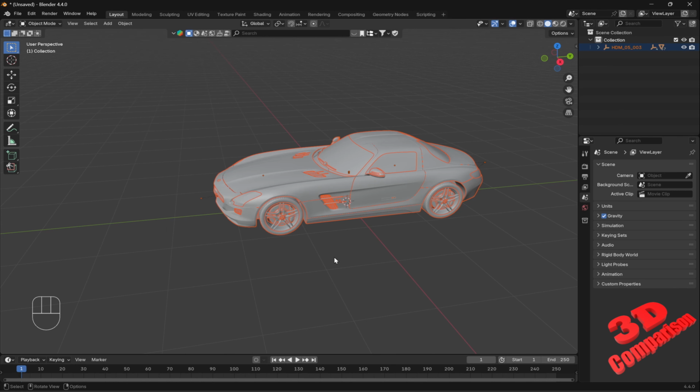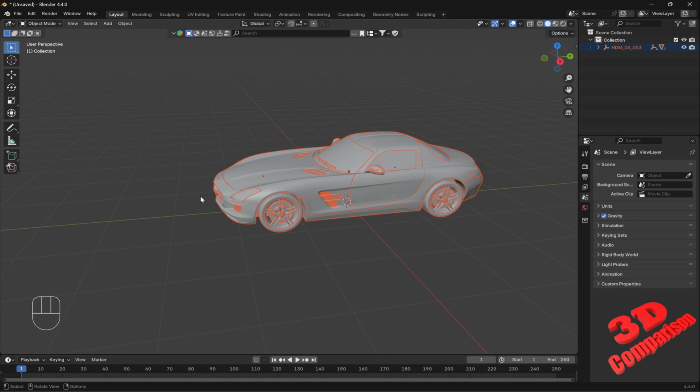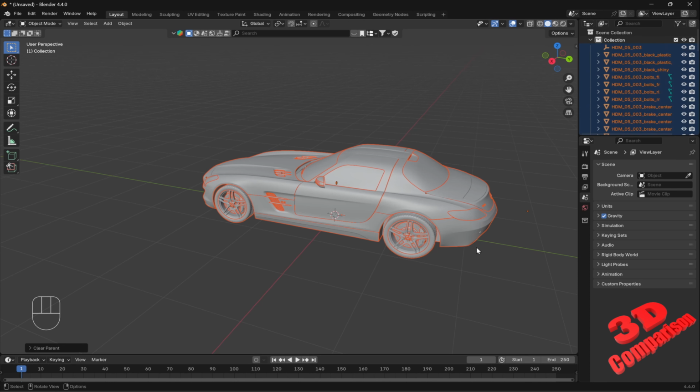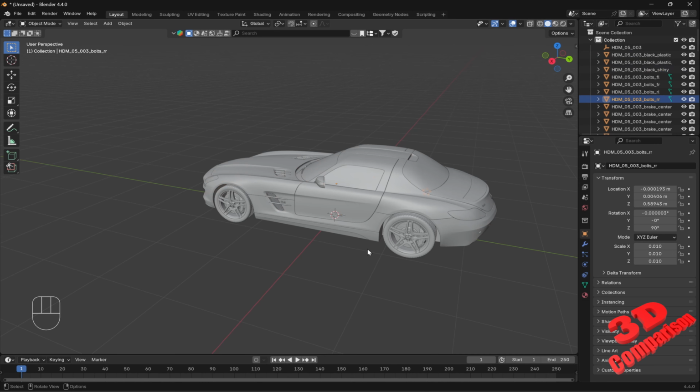And if I'm gonna press Alt and P, you're gonna see that those dotted lines will disappear. So Alt and P, we want to keep the transformation, so the current position of all the components. And over here within the collection, we see that all the meshes are no longer under that, let's say, subassembly. They will all be individual over here.